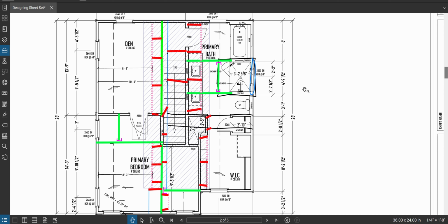I'm going to find a place that this guy was in this front corner here. So I'm going to keep him in mind and move him to the appropriate place. He was right here on the other floor. Okay, so the first thing I can think about is anything that's in the wall, I can pretty much forget about, but I'll leave the dot on there to remind me when I'm framing that, oh yeah, I have a special thing here. And anything that is not on a wall is going to be something to keep in mind when we're designing those beams. So for example, there's a load right here in the middle of the floor.